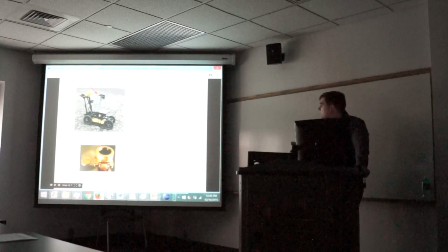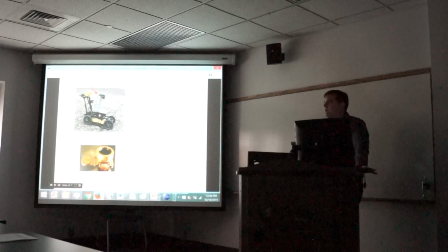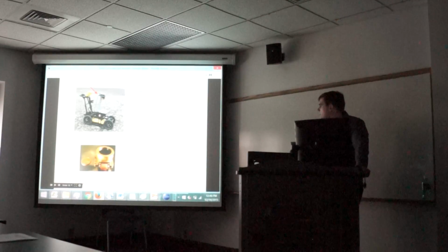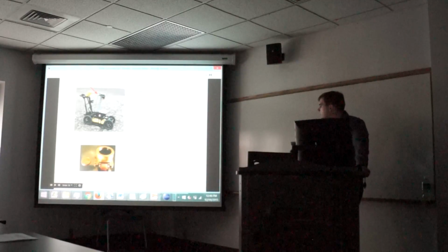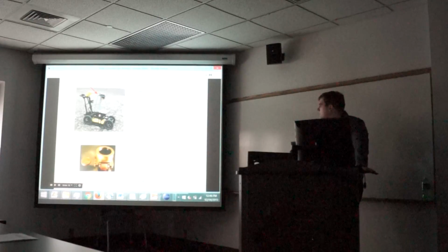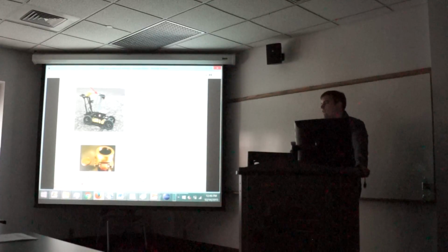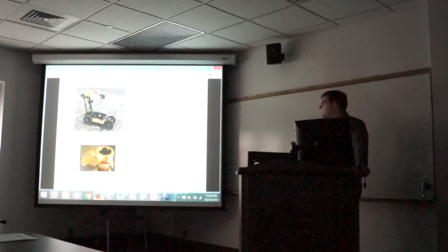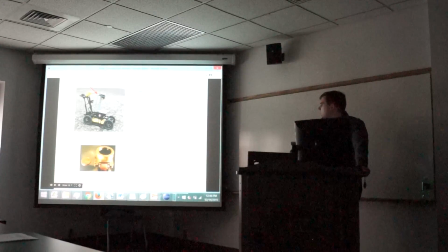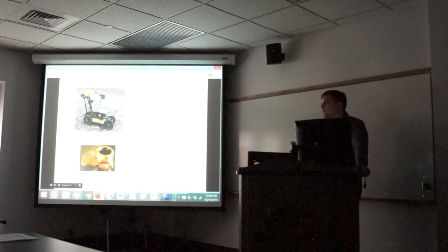And this column is their percent error at the end using visual odometry, and this one is visual odometry combined with the sun sensor. And so for their 300 meter treks, or the ones in that range, there's about 6% error, 4, 11, 4.3. So we were really close to the visual odometry. Sometimes it was the same error, and other locations it was drastically reduced using the visual odometry and the sun compass to correct.